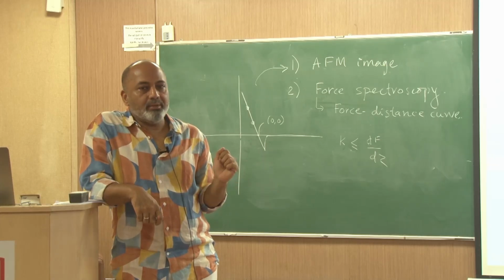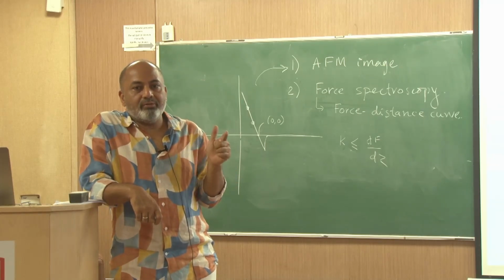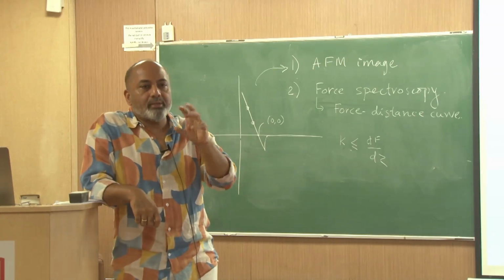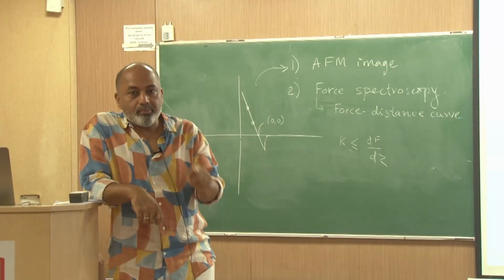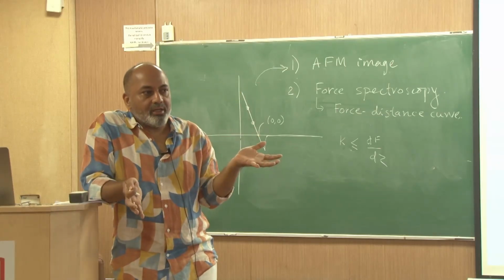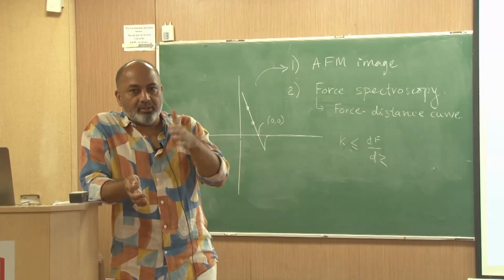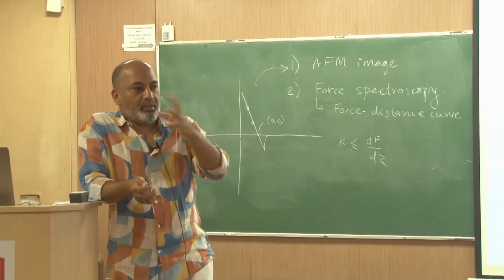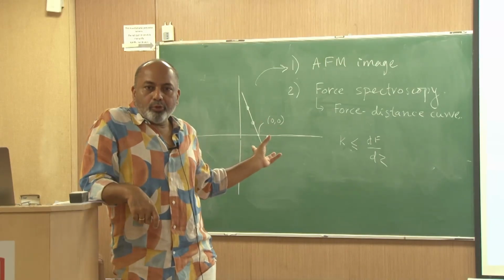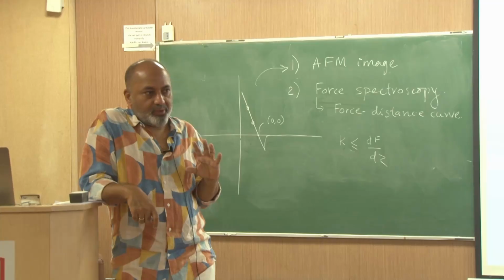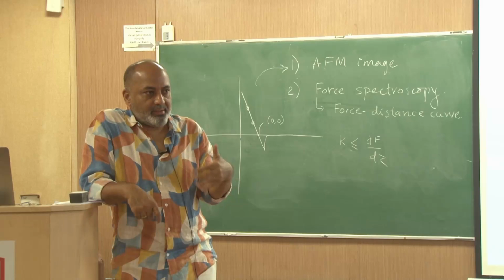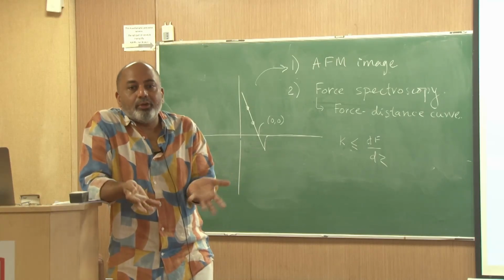As a result, what will happen? I want to hold the temperature fixed at 25 degrees, but it will keep oscillating between 30 and 20, or maybe you can keep that range a little smaller, but it will always keep oscillating like that. So we say the temperature of this room is held constant, but it is not really held constant. It is fluctuating, going up and down throughout as the thermostat is tuned. Here we want to hold the force constant in a similar way, but the thermostat thing is not active. This is a controller trying to control the room's temperature, but it is not an active controller.